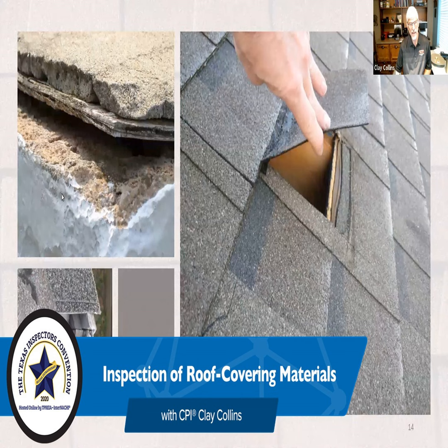But how often do you see what might be a very steep pitch that has two valleys come together, and you might have down in that valley and eave a very small area that might be 3 foot wide coming to a point where it's funneling all that water down the steep pitches into a valley that comes down there, and it ends at the bottom with that almost flat or less than 1 in 12 pitch. That area hopefully is protected better by the underlayment than any other area, and hopefully the installation and the design and creation of that valley is going to be better than any other area.